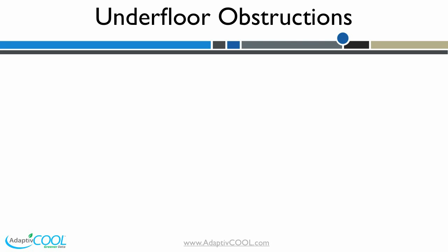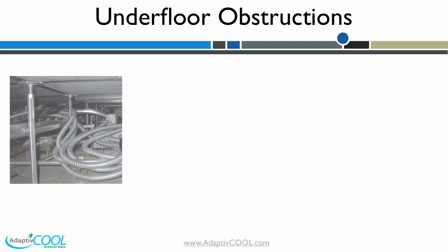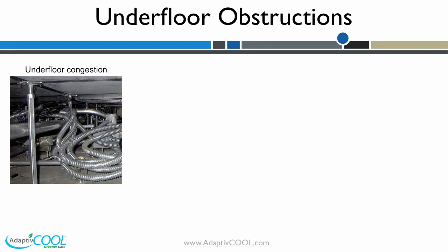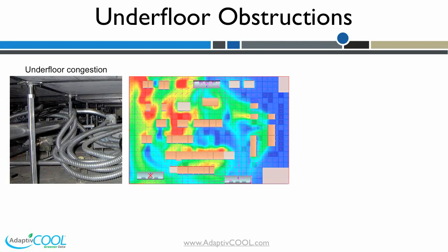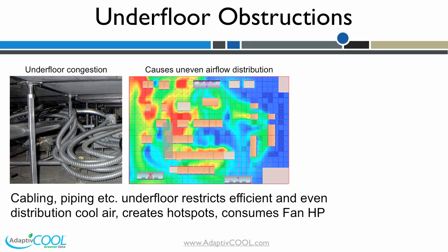In the previous chapters, we covered airflow impedance and its effect on data center cooling. The underfloor airflow impedance affects the airflow volume and distribution in a data center. It is hard to change the distribution much with just passive approaches. The primary cause of high airflow impedance is the floor height itself. Some of the older data centers with 10 to 12 inch floor height face the challenge of pushing air through a constricted air path under the floor.